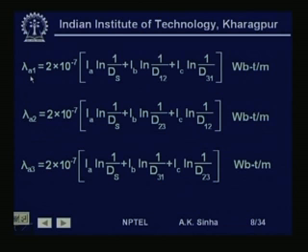So, now let us find out the flux linkage of phase A conductor in the first 1/3 position of the conductor. This we write as lambda A 1. This is equal to 2 into 10 to the power minus 7 into I A log n 1 by d s. Here I am writing d s instead of r dash, because sometimes we use more conductors instead of one conductor. So, we are talking about the self distance, which is r dash for a single solid conductor line.